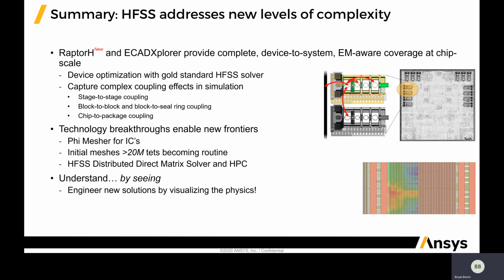It's improving our ability to capture and understand complex coupling mechanisms, be them stage-to-stage coupling, block-to-block, block-to-seal ring, and then those system-level effects, chip-to-package, chip-to-package-to-board. And a lot of this has been facilitated by breakthroughs in mesh technology and by advances in our distributed direct matrix solver and HPC technologies.